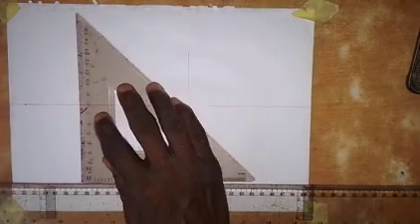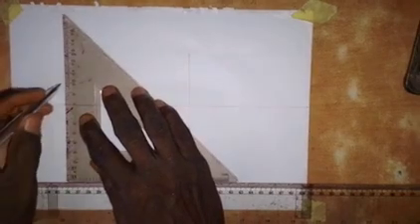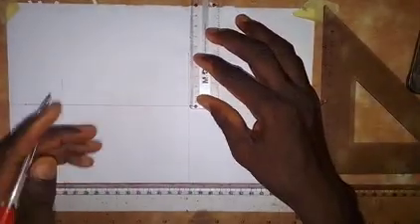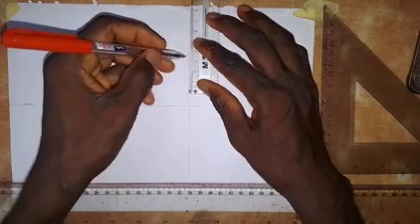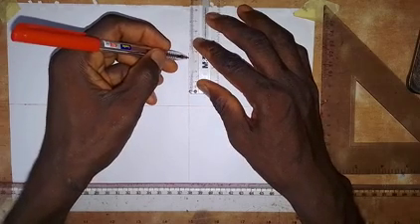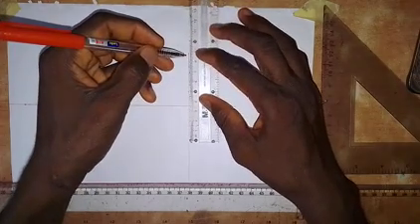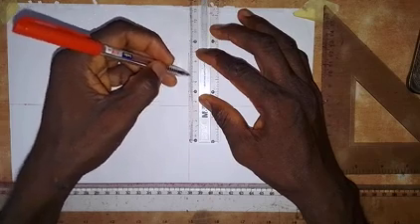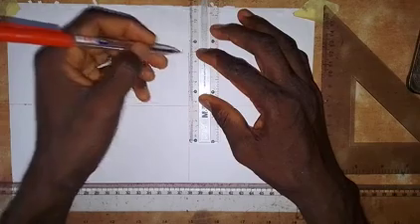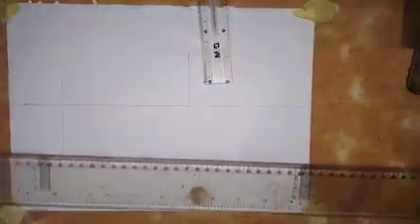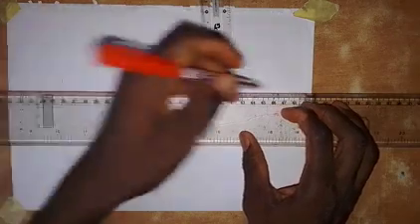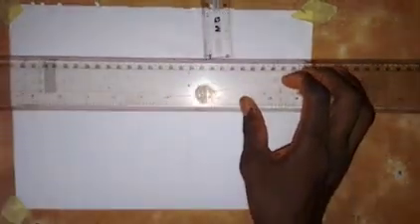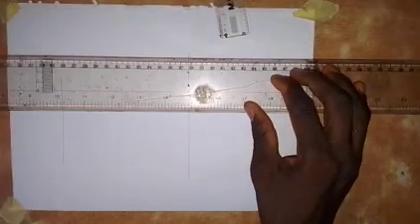Then at this point we draw a vertical line, and we take the thickness of 15 millimeters. So we take 15 millimeters here, and from here we take 35 millimeters up. I can't see this very well. So 35, this is 1, 2, 3, so 35 is here. So we have 35 millimeters. Here we are going to draw a horizontal line on each of these points.